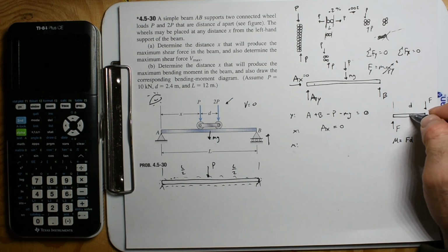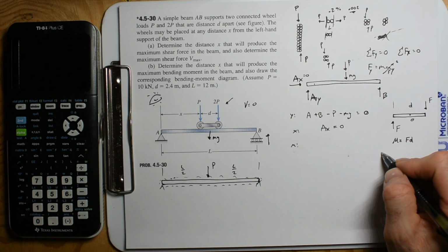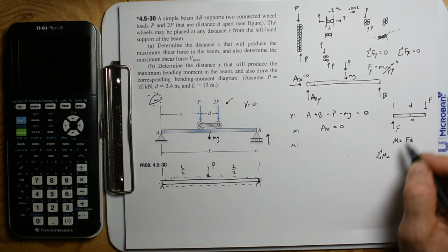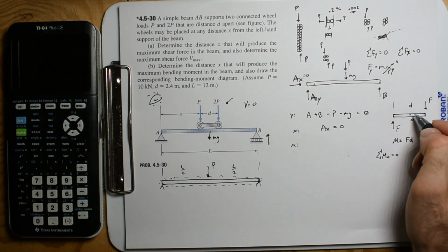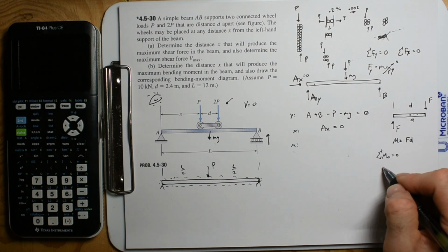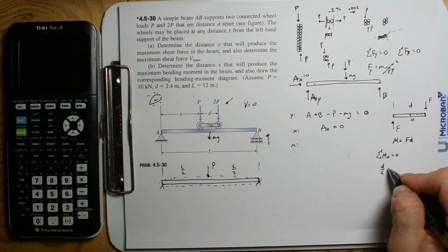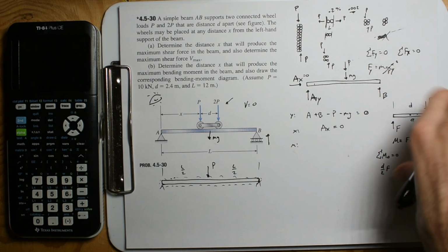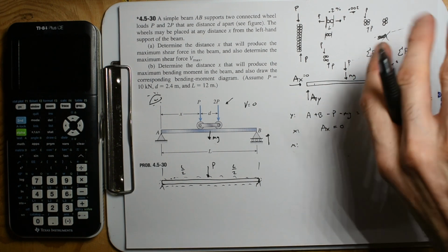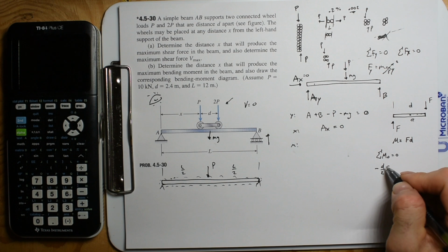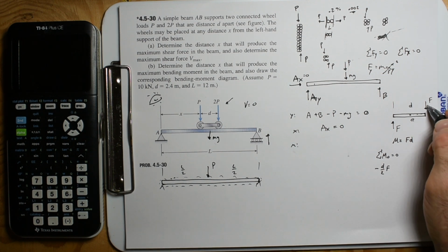And let's slow it down because we're going to have to maybe pick a center. And what we would say is that the sum of the moments about this center are going to be 0. And so let's start. We're going to go over to this force. This force is a distance d divided by 2, and then we run into that force. It's going to cause it to spin this way. That's going to be the negative direction. So we have negative d divided by 2 times that force.